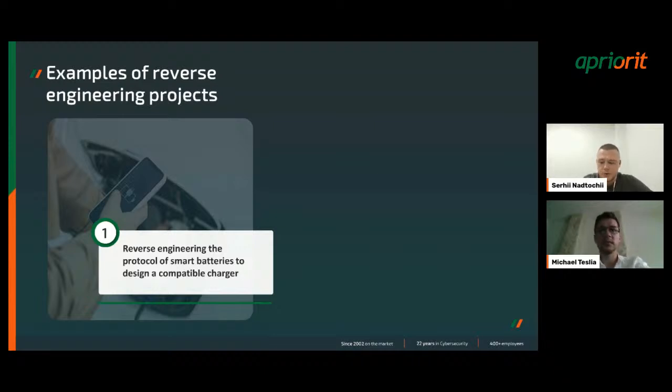We were involved in the process of understanding the protocol of these batteries, because it is not enough just to connect them to the charger and apply some voltage for it to start charging. Some initial communication with the battery should be provided to trigger that process. It was also a useful protocol, as it allows getting data about the battery, for example, the overall voltage on the cells, current, and even the recharge cycles of the battery.